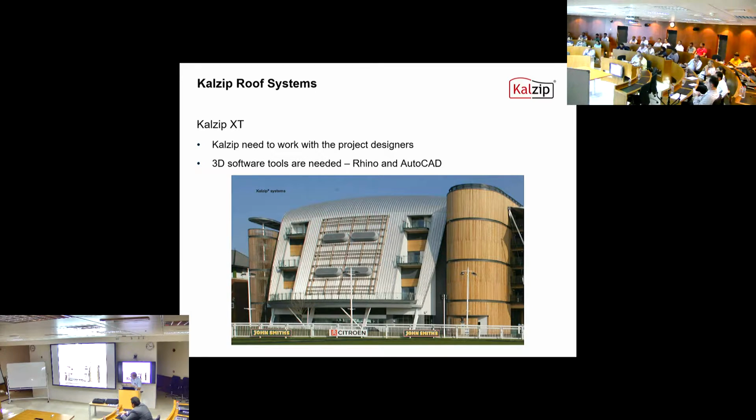So this is where we welded to straight sheets. Yeah, so these are just straight standard sheets. This is where it is welded. So the curved geometry joint is a welding joint. Welded lap joint. Not closed. No, just weld. Continuous sheet, one sheet welded to the other sheet. I assume the weld is the fixed point, right? We can put the fixed point, yeah, to control the thermal movement.